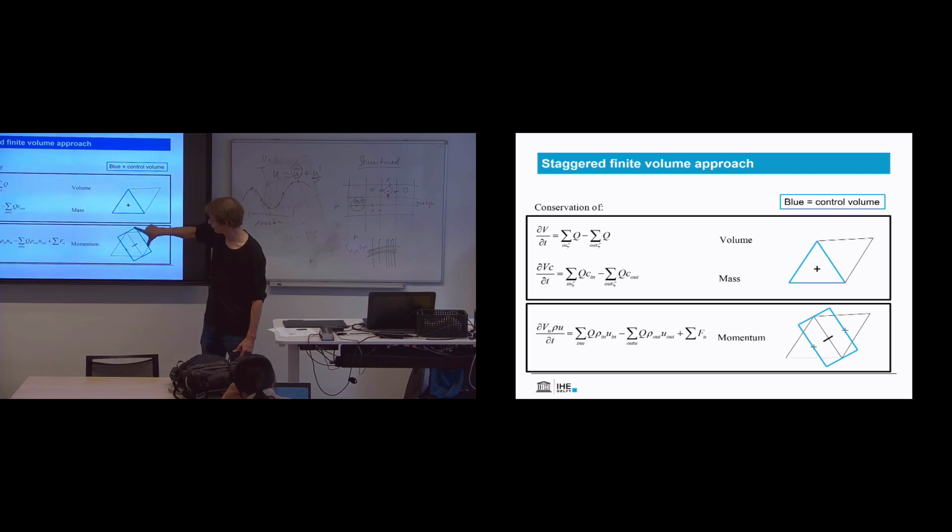So this is just transposed on either side. And then you multiply it by the distance between these two cell centers. And if you then multiply that by the depth, then you get a volume-weighted value for whatever quantity you need in your momentum balance. That's a little bit how it works. Is that clear now? Okay.